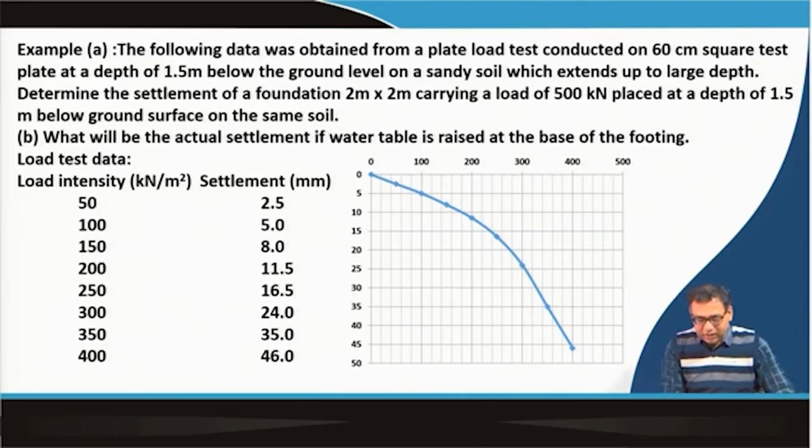So, we can use this data, but as you know, for layered soil also we have to use this field plate load test data with caution, because the plate load test is a small scale test compared to our actual foundation. If there is a layered soil, then there is a possibility that a particular layer may not be influenced by the plate load test, but for the actual foundation that layer may be influenced due to the load coming on the foundation. So, in those cases you have to use these data cautiously, but here it is homogeneous soil. So, we can use this data for our real foundation also.